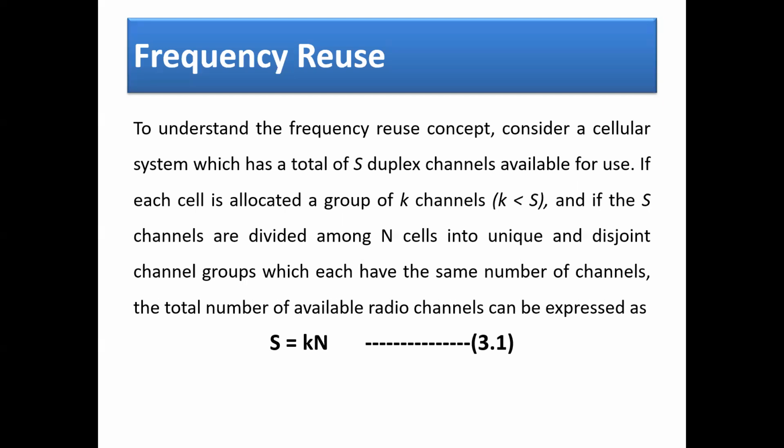If K equals S, it means we are going to allocate the whole channels to a single cell. At that time, we don't have clusters, and we don't have the ability to use frequency reuse. Okay, it's a very important point.